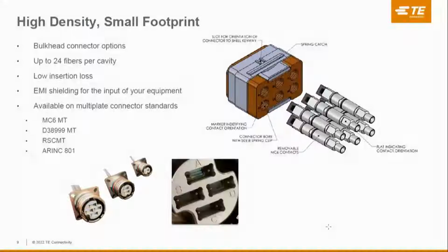Different ways of having different types of connectors, obviously depending on your need. Whether they are single connector, very small footprint. We're talking a connector with a diameter of 13 millimeters, which can have up to 24 fibers, for example, and a much more complex one, again depending on your design, where you can stack up all your optical flex, but having all your fibers going through the system on the input and output side in one connector only. So again, space saving is of the essence here.